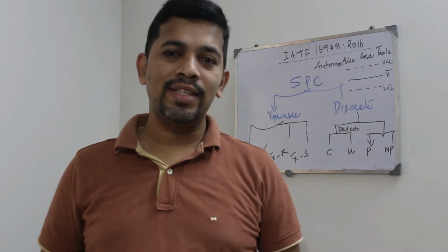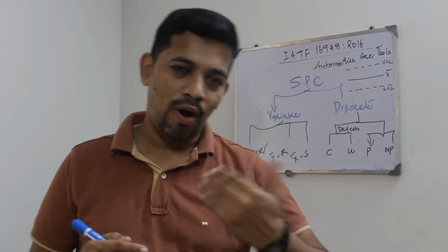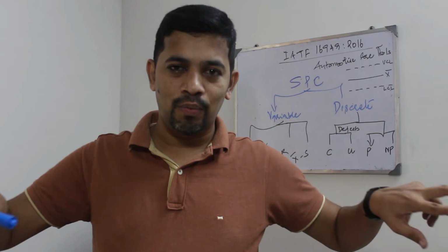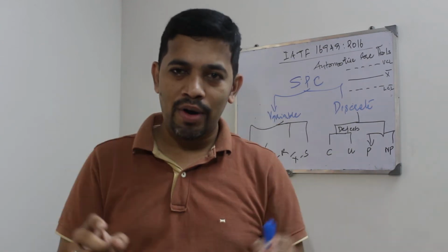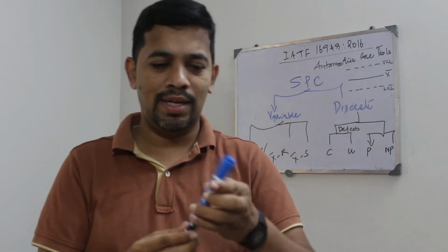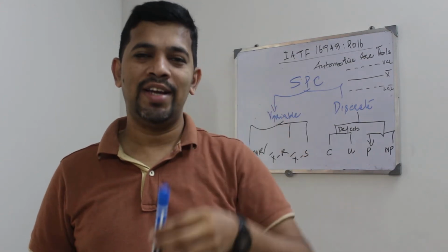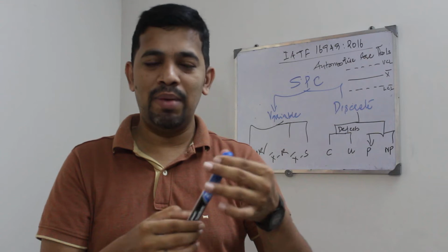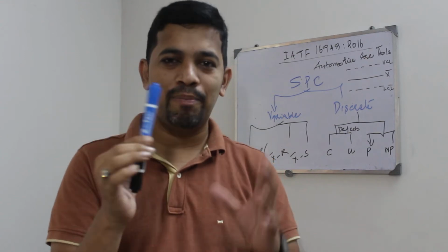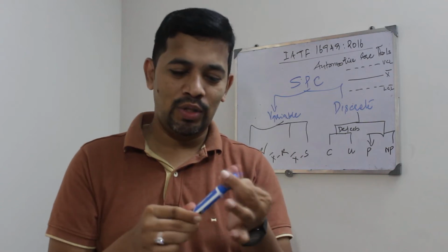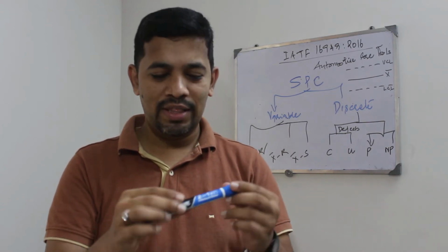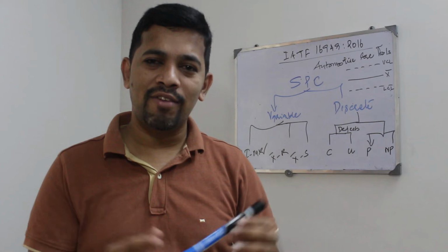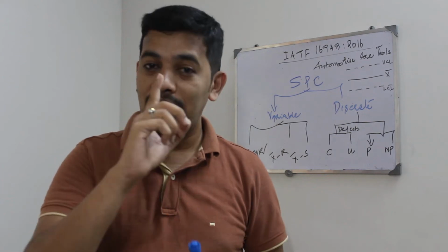And then discrete is the other side. Discrete is attribute data, where you can count or classify, right? For example, you have 2 things, defect and defective. One failed product can have multiple defects. For example, a marker is not working. Defective is 1, but defects can be more. Maybe the ink would have completely dried off, number 1. Number 2, the nib would have broken. And number 3, the printing, the painting, everything would have been removed. All these are factors. In this case, 3 defects, 1 defective.